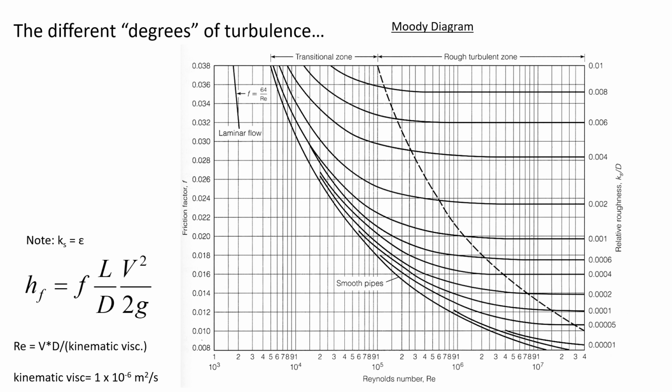So P1 is high, P2 is lower. So water's flowing because the pressure downstream is lower. Or, and it's a chicken and an egg thing, you can also think about it this way. You could think that because the water is flowing from 1 to 2, there is less energy at location 2 because of the effect of pipe friction.